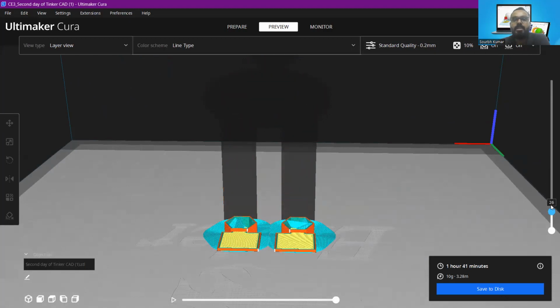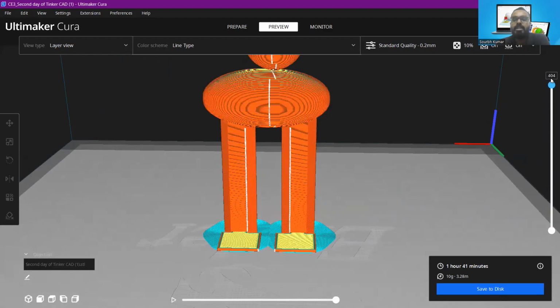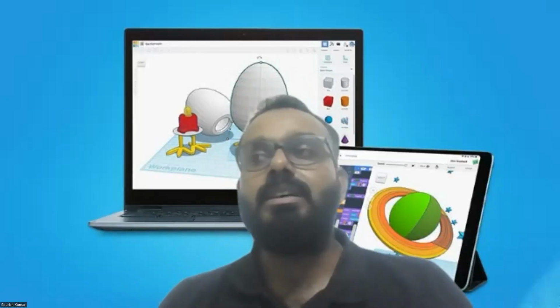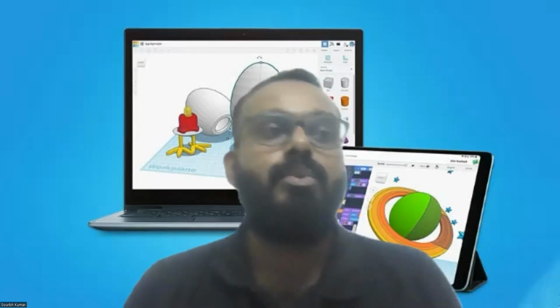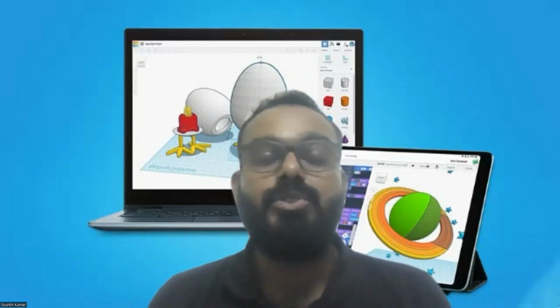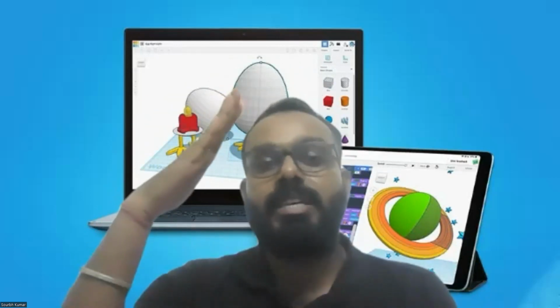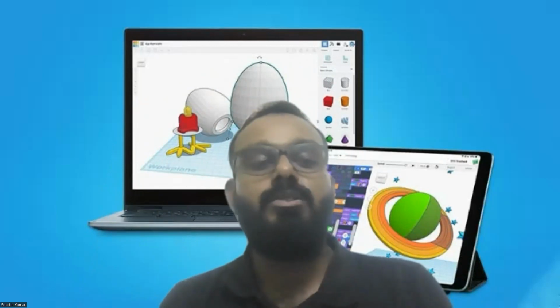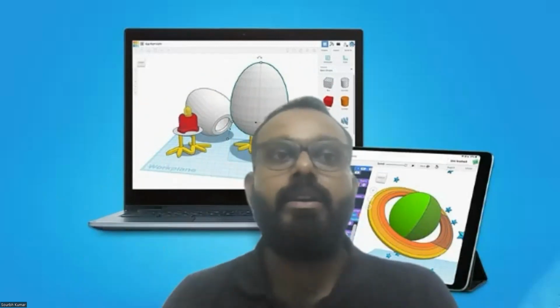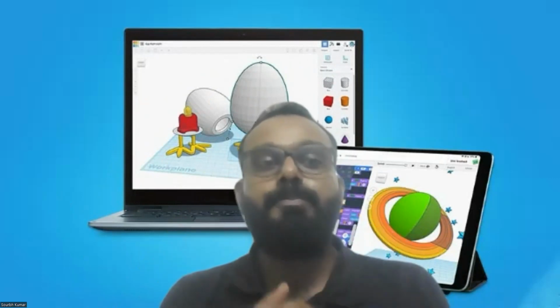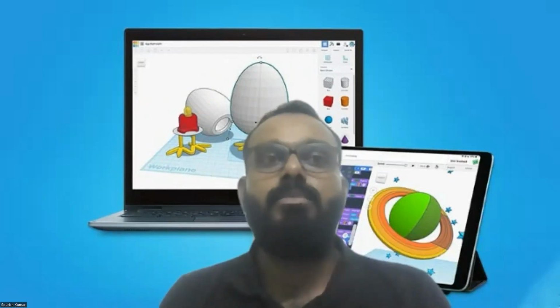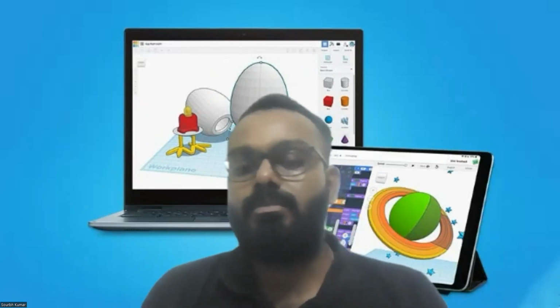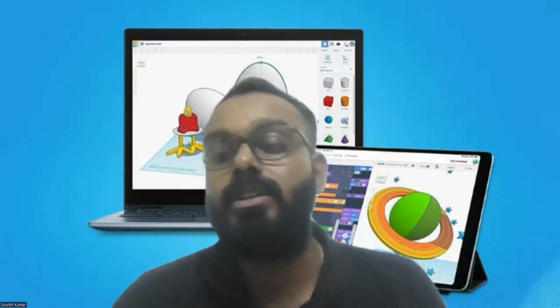The reason we provide supports is to handle overhanging portions, like a cantilever beam structure or any inclined portion. You cannot print something in the air, so you need proper support for the overhanging parts in the model itself.